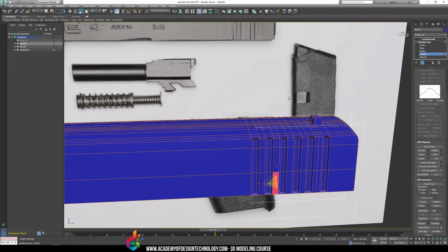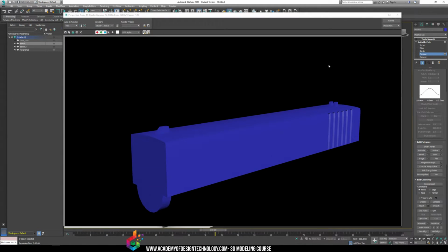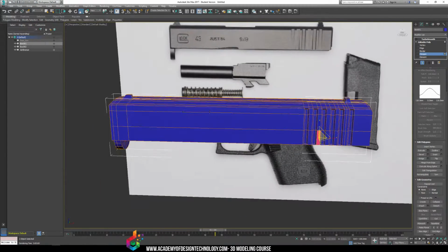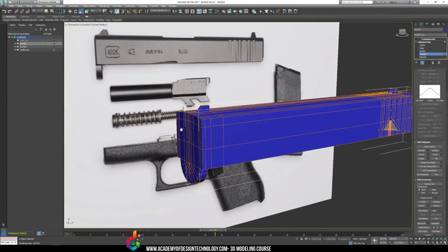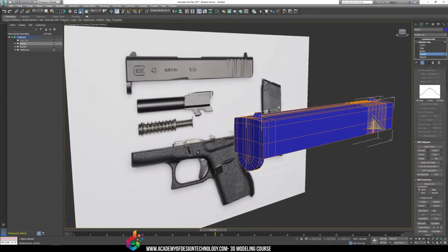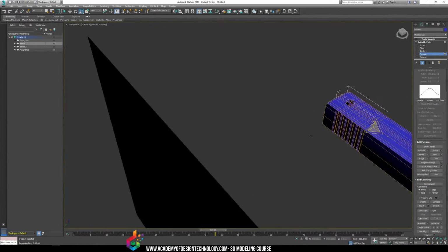But like I said, ideally at first, just work with your turbo smooth. You might not even need a turbo smooth or mesh smooth if you throw enough polygon detail into the low res mesh. For this situation, I actually might just smooth out the sides because it might be less of a hassle, and I might just leave it as is with nice rounded edges, and then I'll boolean out the front. If you forget how to boolean out the front, it's pretty simple.